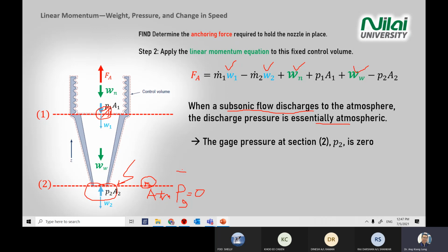Now this is also another trick question, or another area that students will forget when it comes to a test or exam. Every time you have a pressure exposed to atmospheric pressure, the pressure reading at that point will be 0. So your P2 is 0. Sometimes we will give you some hints, or give you a bonus mark in the question.